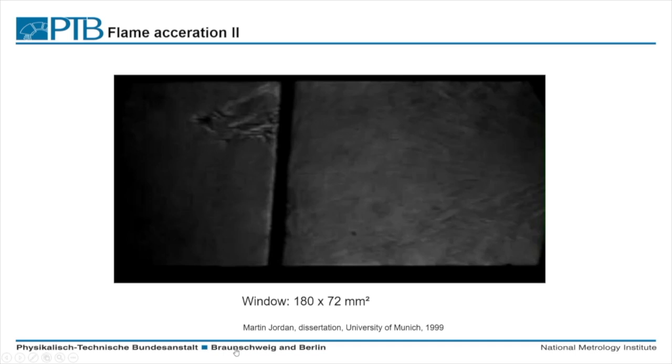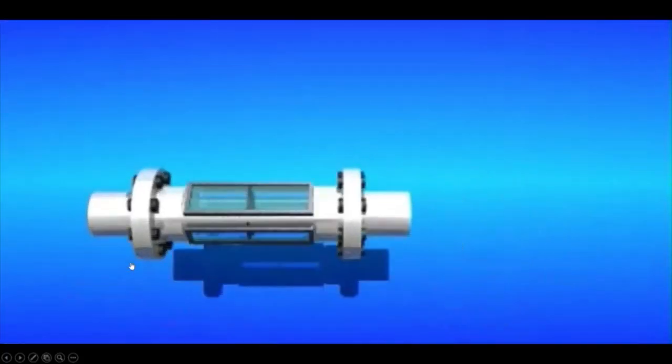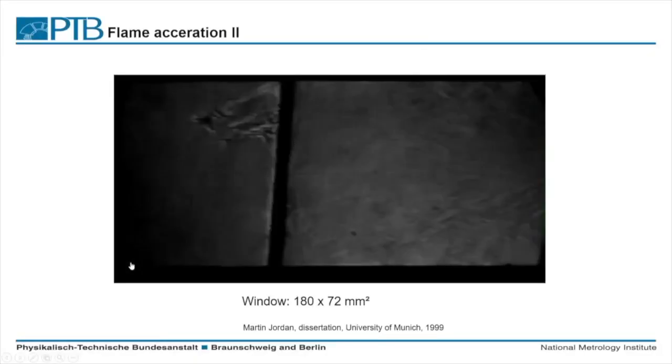So you have a pressure difference here. The flow is accelerated up to the sound velocity of the hot gas, depending on the configuration we have. And what you also see is, so it looks quite slow here, the flow comes with a given mixture, and how fast then the ignition occurs in this large, hot, very turbulent flow region.